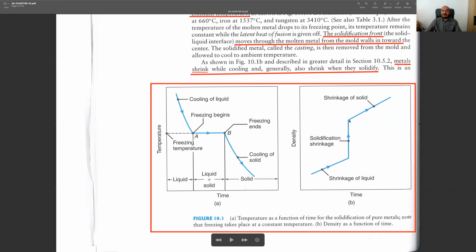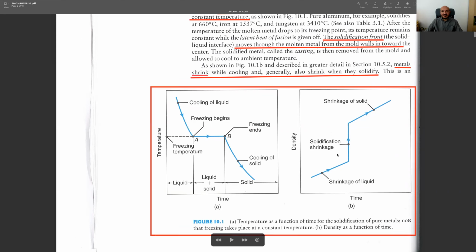If you think about ice making, the volume decreases and the density of the material increases. And this density increase continues even though you have the solid here, for instance, it continues shrinking, but obviously this shrinkage percentage is not high, it's somehow similar to the shrinkage amount in the liquid state.